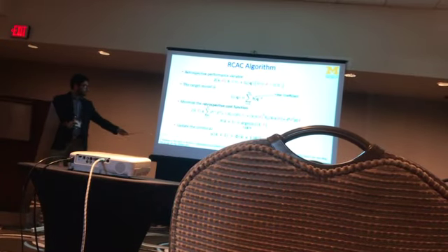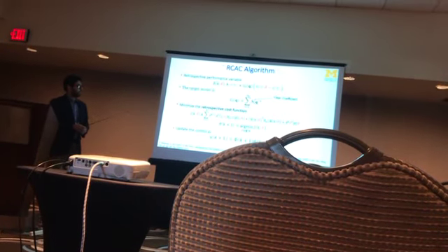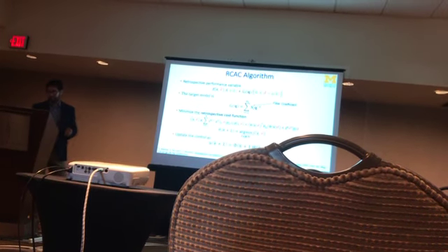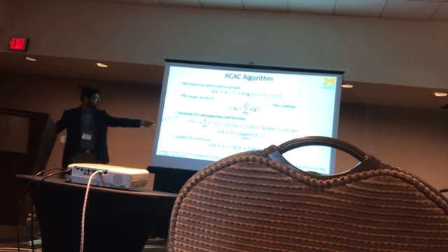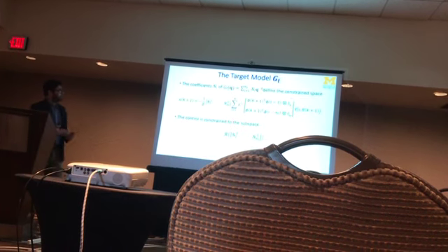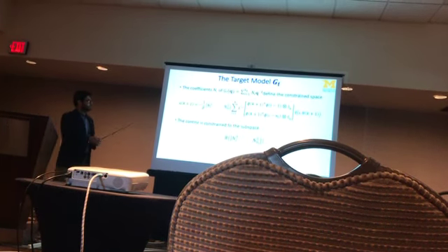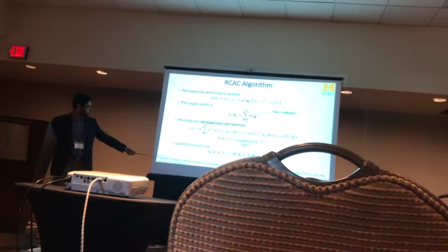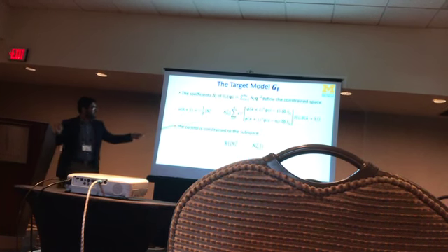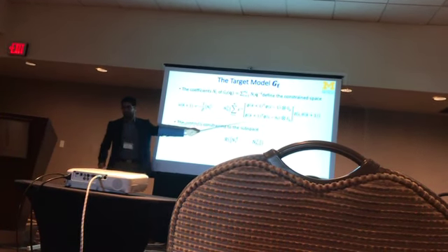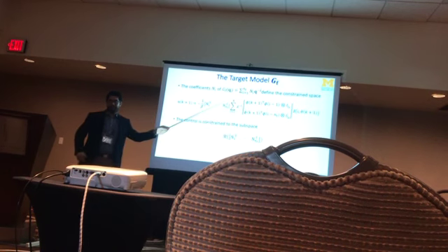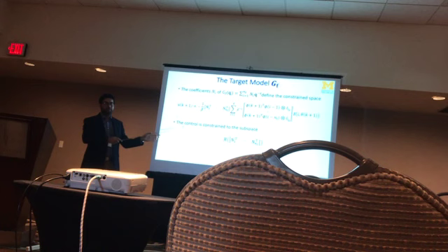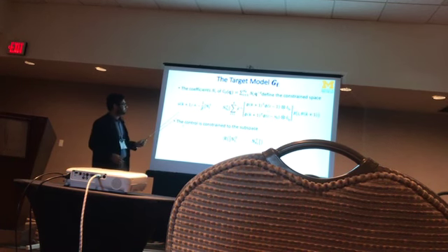Now, like I said, this paper actually goes into a lot of detail about multiple interpretations of this filter GF, but I'm going to use a slightly different interpretation of this filter GF. Once you choose this filter GF, we can do some algebra, and we can write the control input, which was this guy, as actually this guy. So that's a matrix times a lot of data. Now this is only for analysis. That's not how the control input is computed, but when you write down the equations, you can express the control output as this.